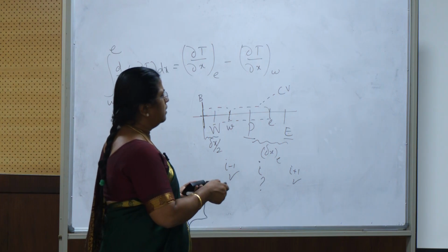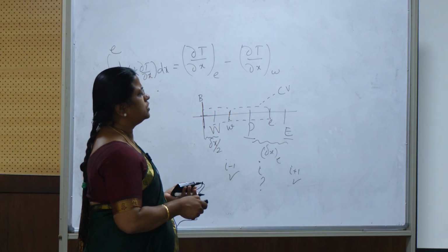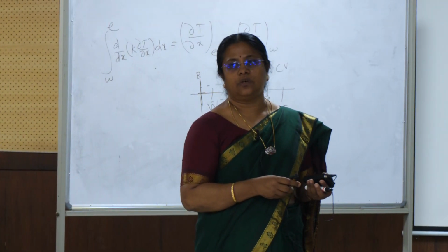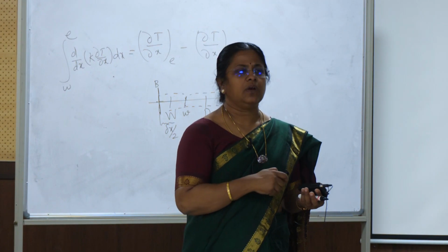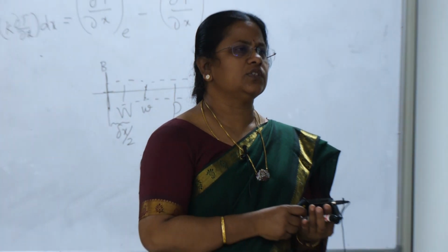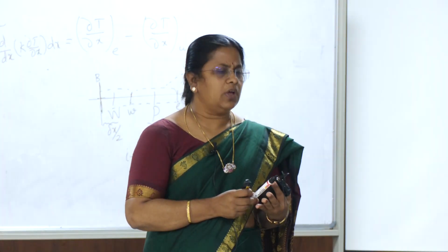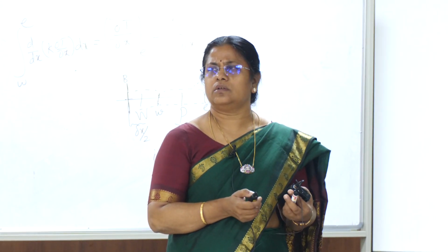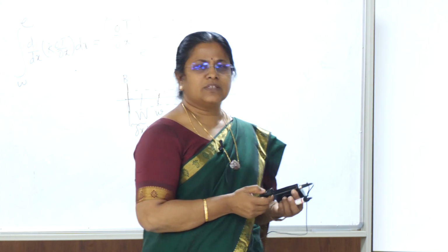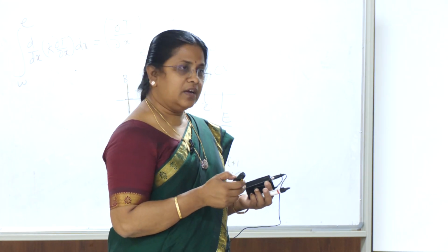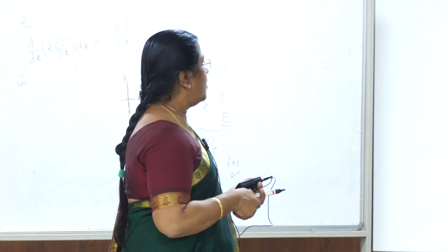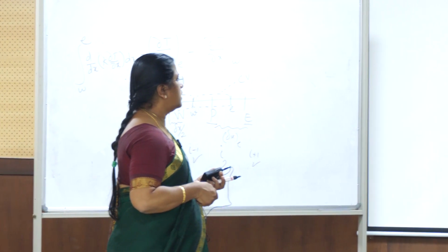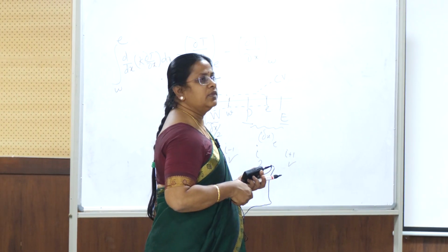Again, we are repeating the same thing, over relaxation and under relaxation. That means whenever we get oscillations in the solution, how to control that? That is based on the over relaxation and under relaxation method. In numerical methods, we would have come across SOR, successive over relaxation. Have you heard or not? No? Successive over relaxation, successive under relaxation also there. The same knowledge only is applied here: how to use the previous one and the current one to find out the current value.